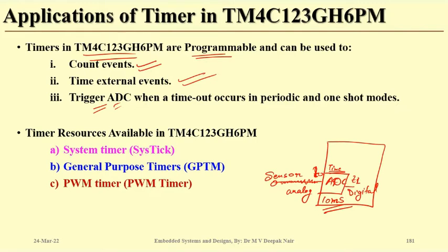So the timer can not only inform the microcontroller, but it can even work with internal peripherals, like the ADC in this case. This is one of the major advantages of using a timer. Remember, the ADC will not convert the signal at that very moment itself. It will take some time. Therefore the timer can apply a wait event and then read the data, apply again a wait event, read the next data, and so on. So this is very important.